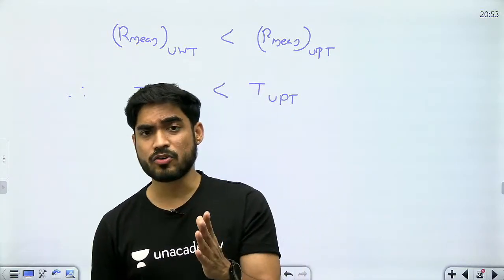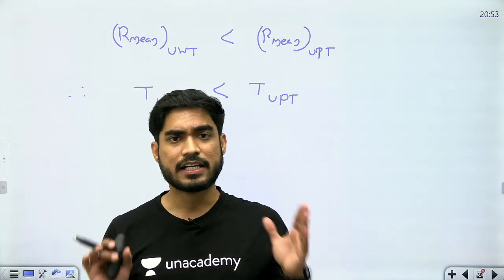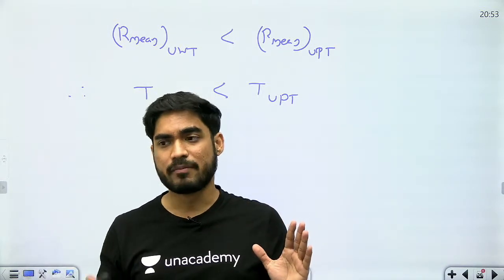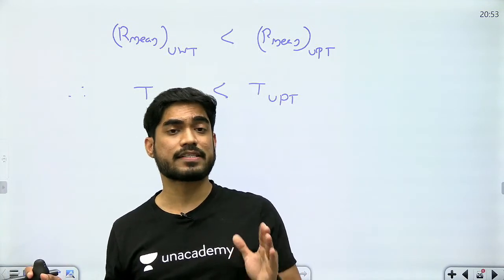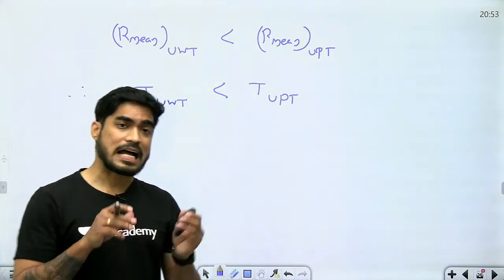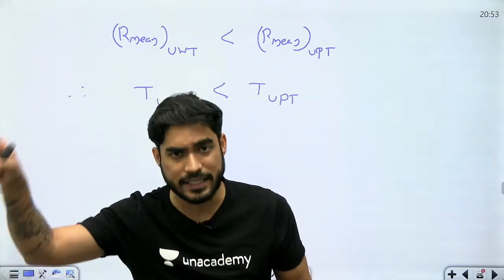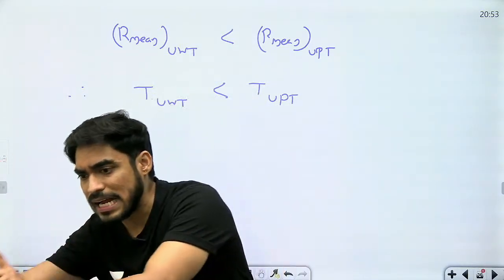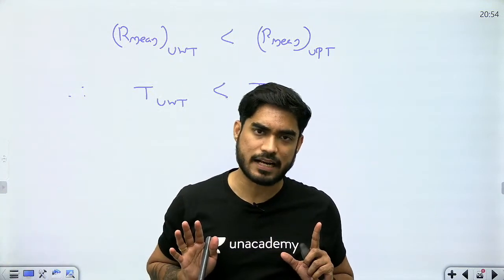So when the clutch is new, you are safe. You need 100 Newton meter, you are getting 100 Newton meter. But when the clutch becomes old, then you will fail, because then the torque transfer will reduce. So beta, if your torque transfer is going to get reduced later, then you will assume that that is the maximum torque I can transfer, right?